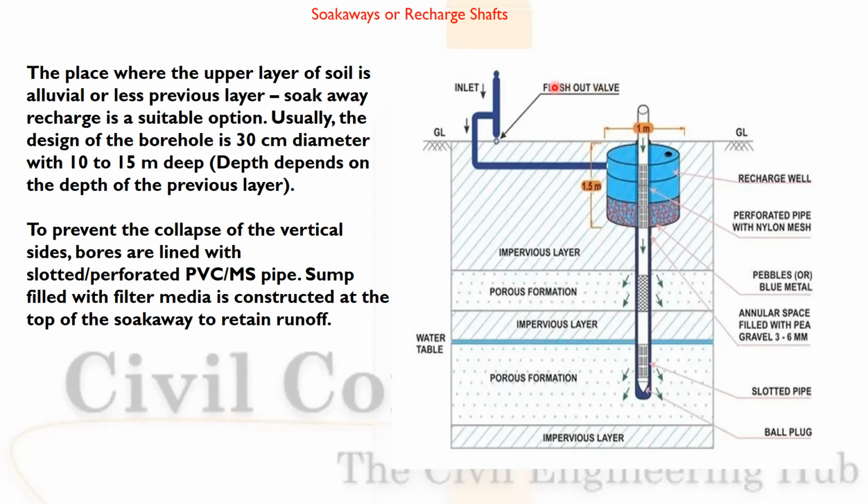Here you can see the flush wall. This is a recharge well. Perforated pipe with a nylon mesh. Here the impervious layer, here the porous formation. In this recharge well you will be having bubbles and everything. Porous formation, and then the water is just recharging the borewell.